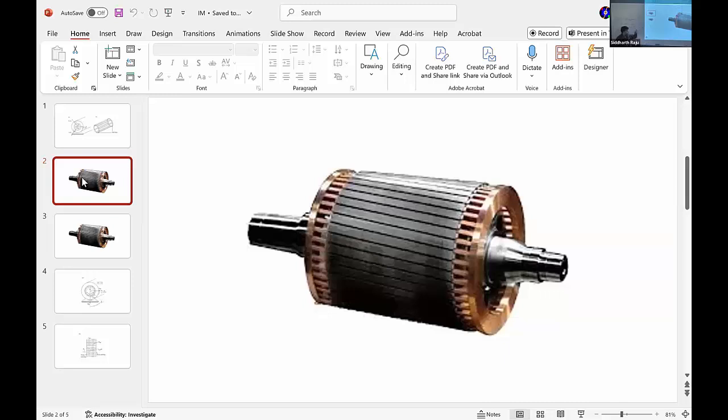And that's the reason we introduced the iron core in the rotor as well, so that when the magnetic field goes through the pathway, it has just this tiny air gap Lg. If there was no iron core, just copper bars, then the Lg distance becomes very large and your magnetic field will become extremely small. So we put that iron structure in between.